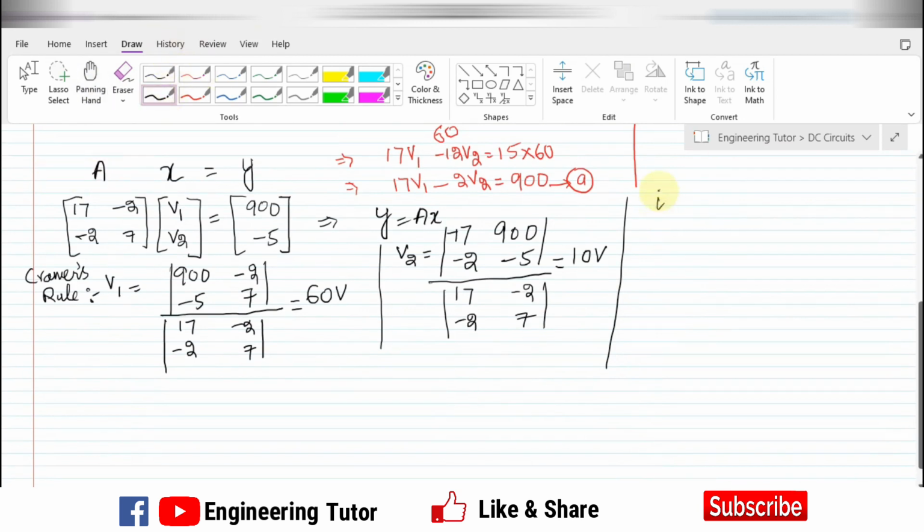So the value of I1 is equal to V1 minus V2 divided by 5. So the value of I1 is 60 minus 10 divided by 5, so ultimately we will get 10 amps. Okay, so this is the 10 ampere current which we had to find out. So this is the solution of part A.